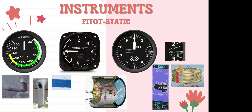Now, one thing that's really important about our altimeter, and some of you may have experienced this, some of you may not have, depending on where you're at in your training, is that when we fly cross country, our barometric pressure will change. So our barometric pressure at McClellan may be 30.01, but then we fly up to Chico and suddenly it's 30.19.